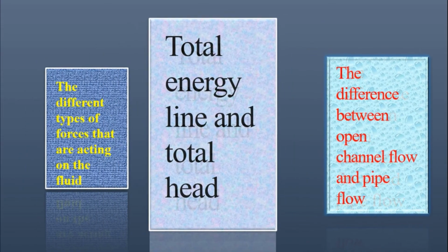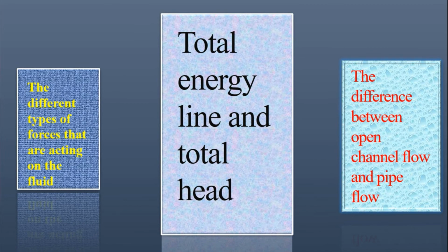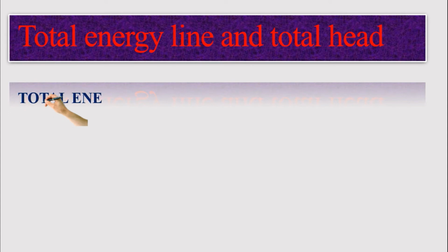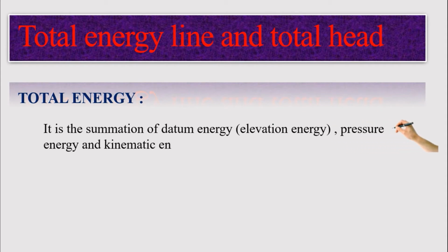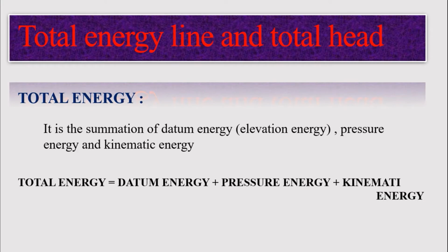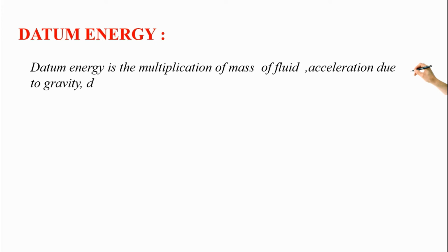Our next topic is total energy and total head. Total energy is the summation of datum energy, that is elevation energy, pressure energy, and kinetic energy. Datum energy is the multiplication of mass of fluid, acceleration due to gravity, and depth of fluid from datum to the channel bed.